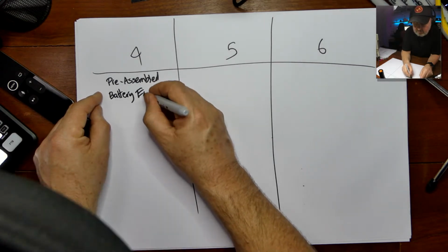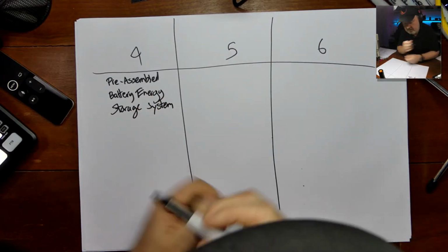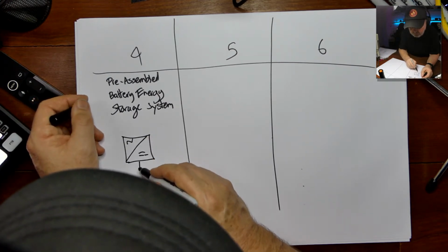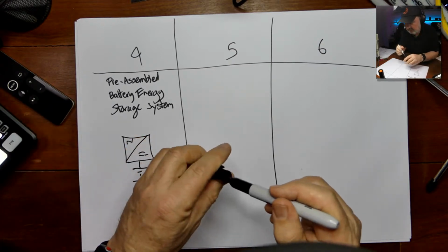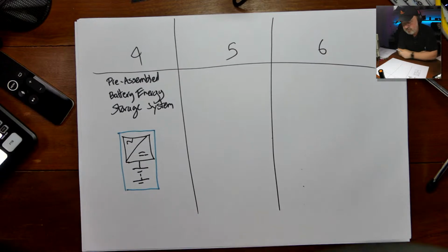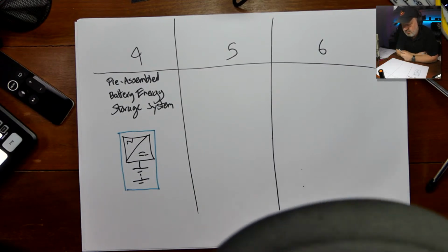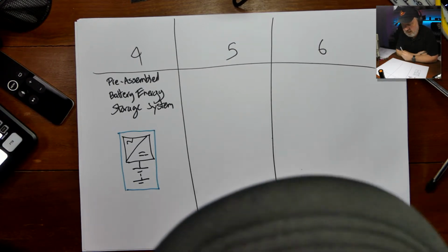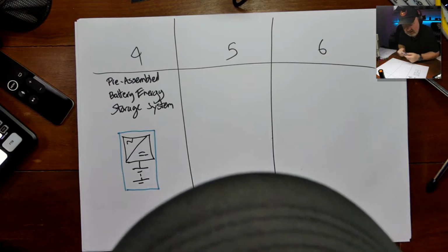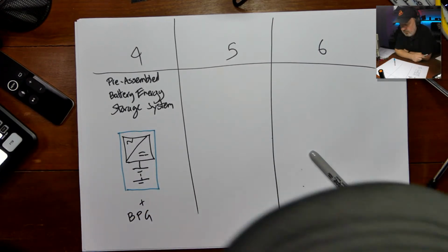That's where the acronym BESS comes from, Battery Energy Storage System. It's easy to think of this as an all-in-one. If I draw an inverter, which technically we refer to as PCE, power conditioning equipment, and draw a battery, and then put a box around that, it doesn't literally have to be a box, but a pre-assembled solution encompassed by that blue line is a BESS. It also has one other condition: it has to comply with a quasi-product standard called the Best Practice Guide, a collection of international test requirements for lithium-ion batteries. BPG compliance is also required.